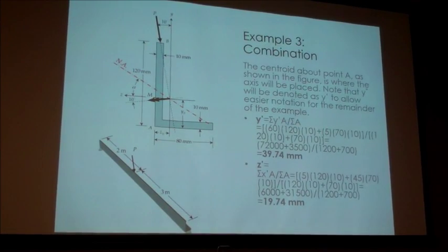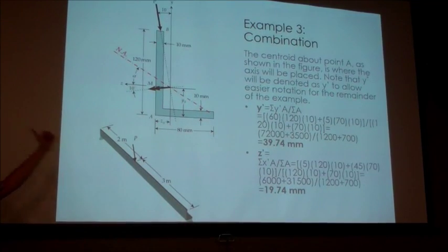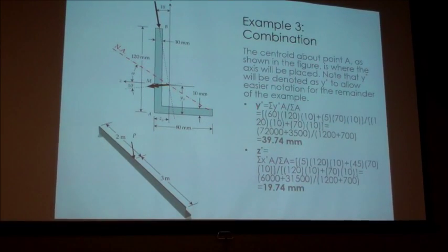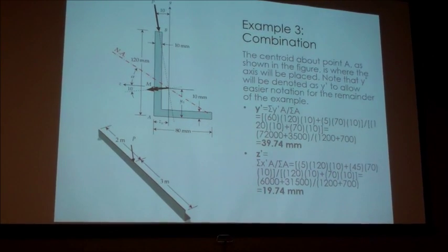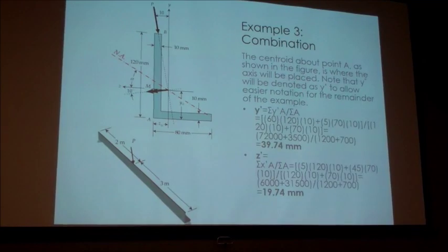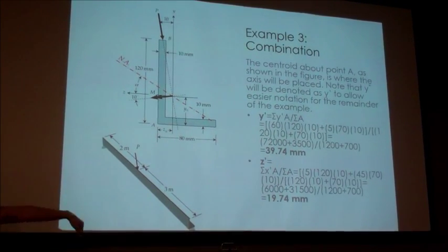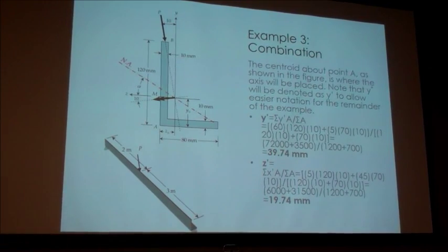That's this diagram. So alpha in this case, because it is zy, alpha is from the left because z is positive to the left. And then obviously this is an angle section, and then the force is coming at an angle 10 degrees from the y-axis. And then we have to have this 3D of what the actual beam is because we need to calculate the moment later.